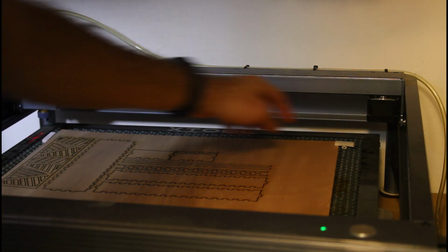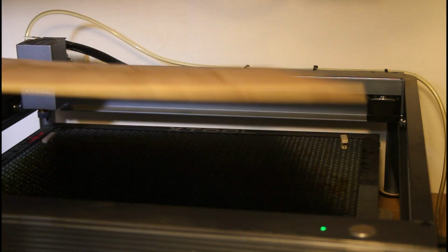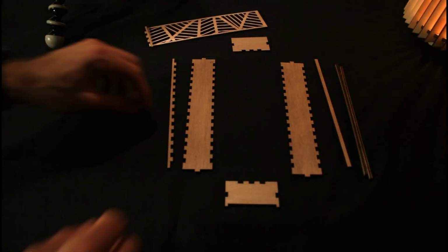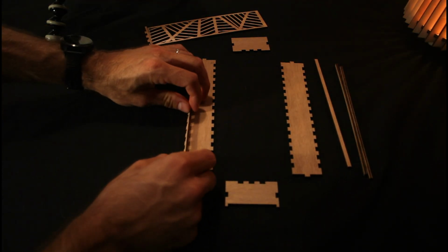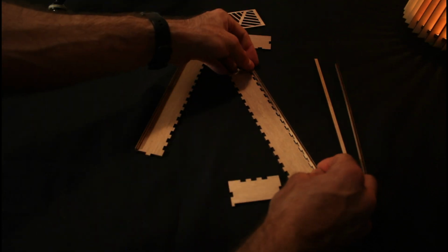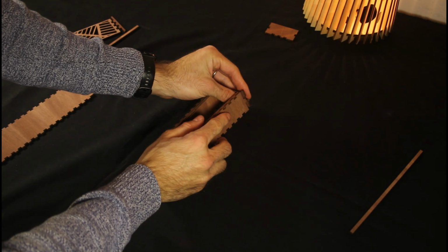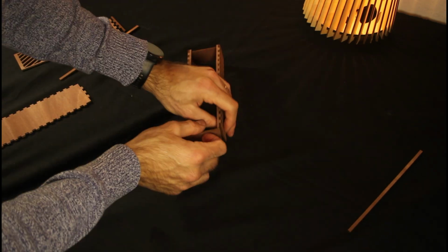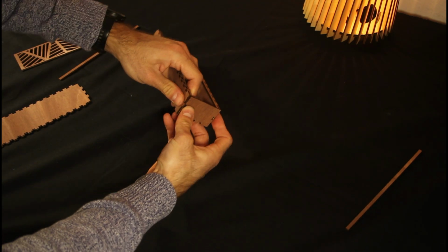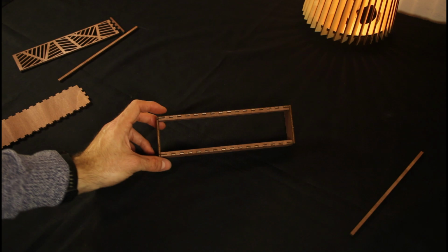In this case, assembly is slightly more involved. Start by attaching the upper lips to the side faces. This will form part of the sliding lid rails. Next, assemble the 4 outer faces of the box. You can either glue the joints or ensure they are tight based on your curve settings. Make sure that these 4 faces are square.